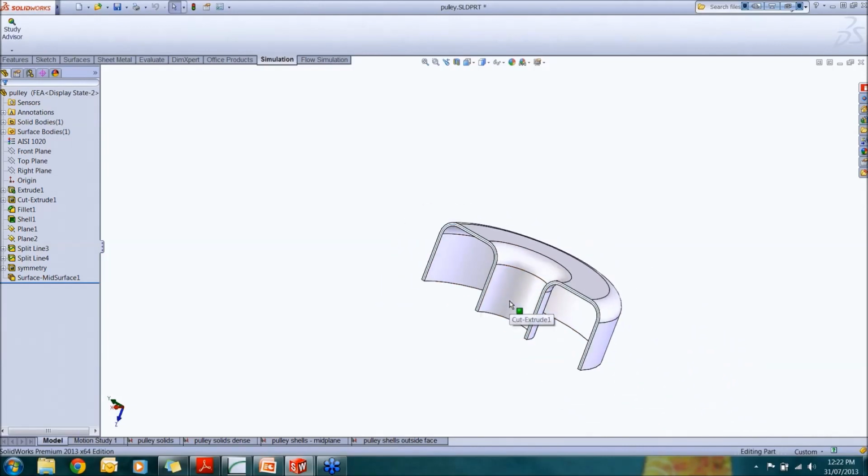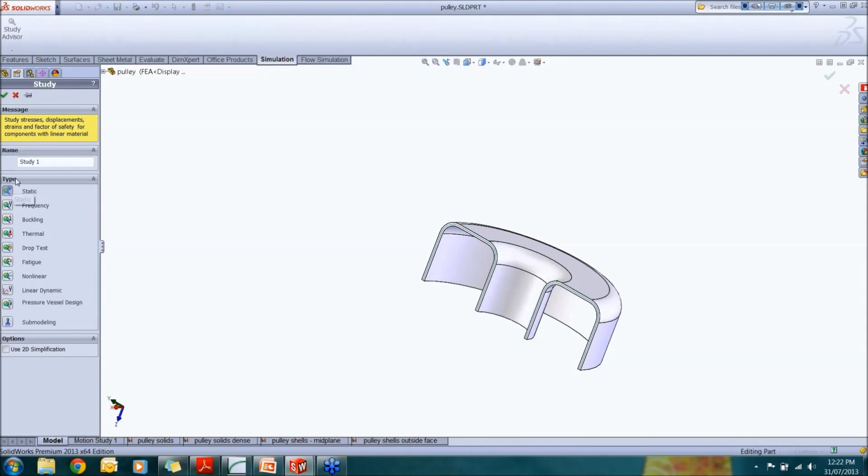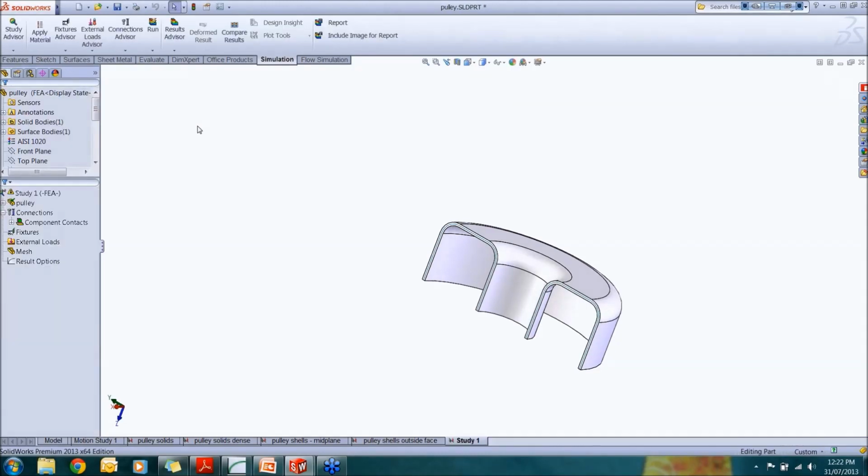Alright, so we have created a middle surface here in order to put the shell elements on there and perform FEA analysis, and then we have the option to see the stress on the mid surface, on the top surface, and on the bottom surface without really having a lot of elements through the thickness. Now in this regard, we have to click on a new study.